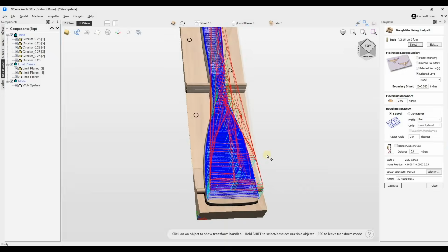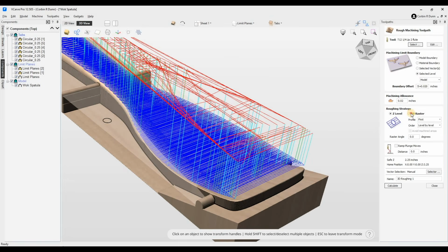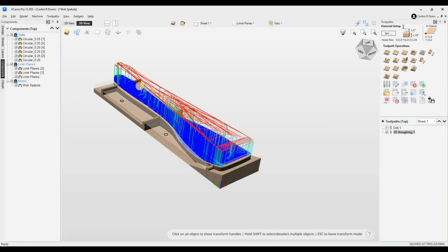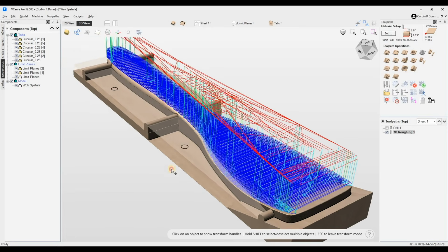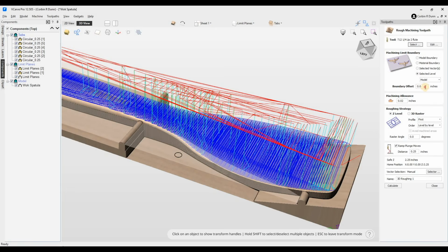And let's see, what kind of toolpaths are we generating? We want to do Z level, profile first, we'll avoid some chip out, level by level, angle, ramp plunge moves by 1/4 of an inch distance. Calculate, close, and it looks like it's not going deep enough. Sorry, it's not going outside the edge.